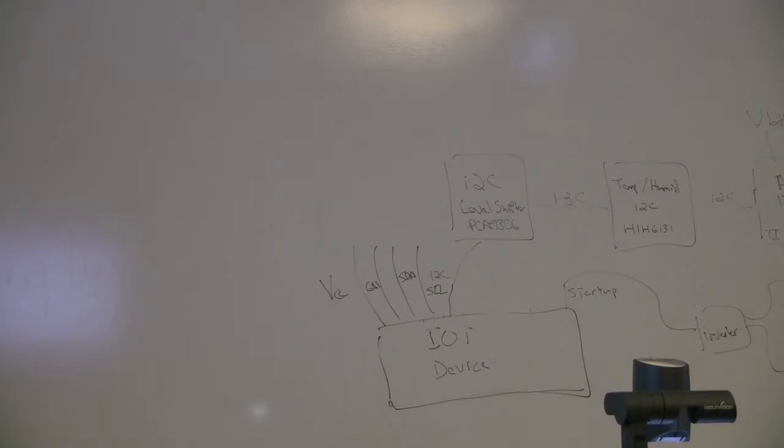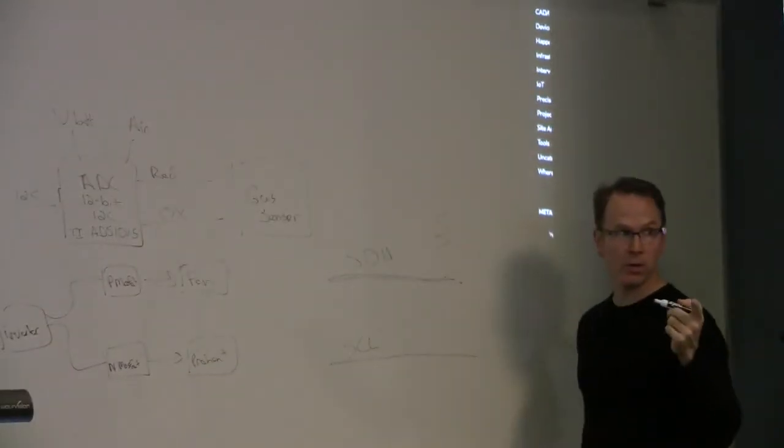Well, operation signal. Let me show you one thing, what little I know, and there's people in here that will add to this, I'm sure. The way this I2C thing works is there's these 2 lines, and they're both pulled up, right? So this, in your thing, from your board, your MCP, whatever, that's pulled up to 5 volts.